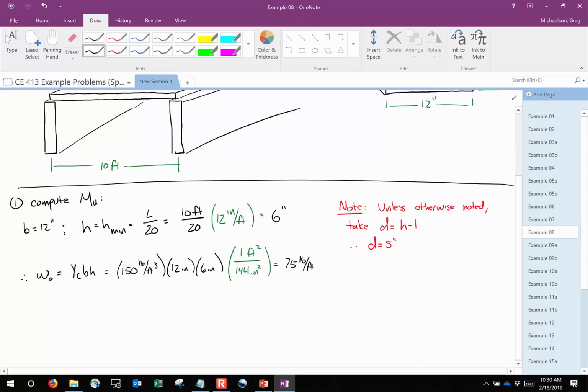This is actually kind of serendipitous because you have a section that's 12 inches wide. What if it was 12 inches tall? Then the area would be 1 square foot, and the weight per foot would be 150 pounds per foot. But this is 1/2 square foot because it's 12 by 6. So what's 1/2 of 150? 75. So that's a really round, convoluted way of doing 150 over 2, but that's basically what we were doing.